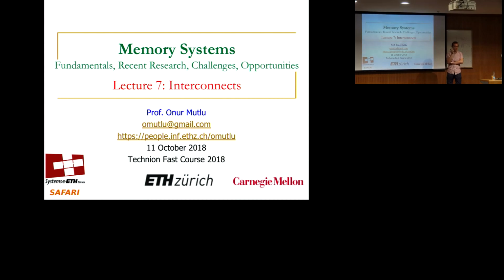There is work. I can point you to them separately if you're interested. I think of coherency as some other substrate that you build on top of these things. If your interconnect preserves ordering, that's good. Ideally you have a bus, right? And a bus enables you to see all of the requests, and it's a point of serialization, and you can order some things. But that goes directly against scalability, right? So if you want ordering, maybe you want to build some other substrate on top of your interconnect.